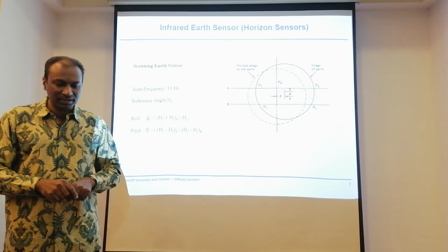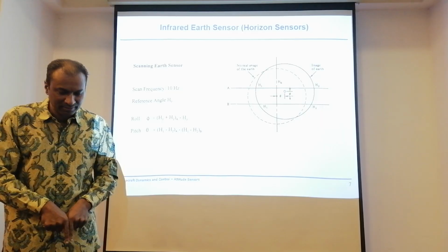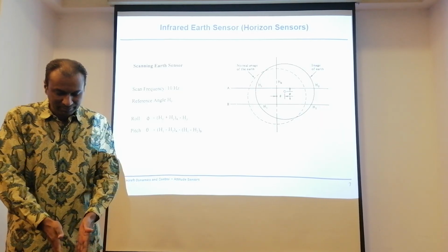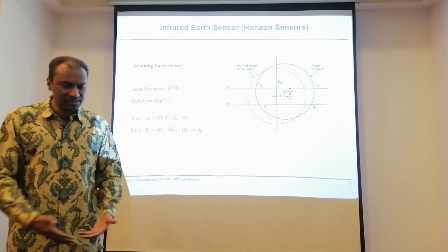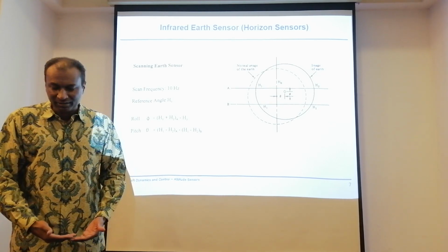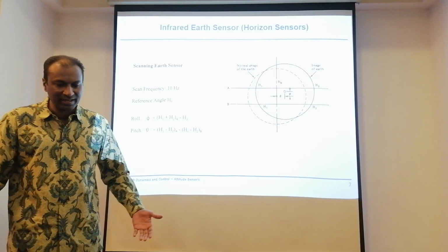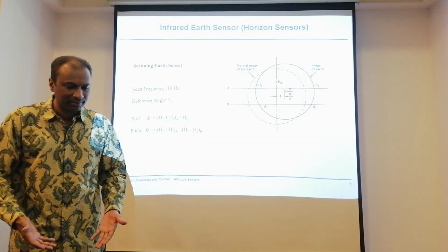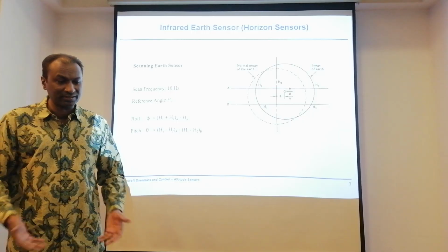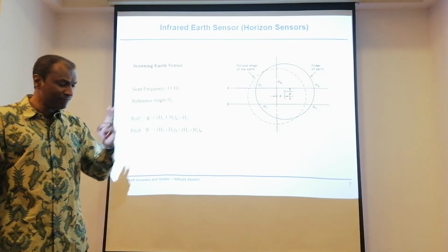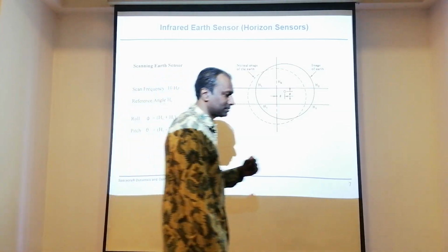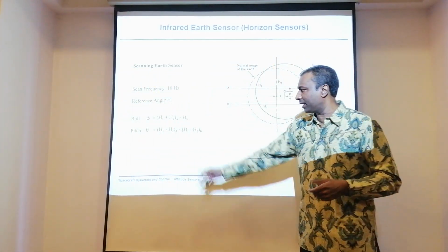But unfortunately, when you look down towards Z, that is exactly on the planet Earth. That means it's all basically the terrain. You can see sea, etc., so that you can't detect. You can't actually have a horizon. So you can only see the land. You can see it all, but you can't have the horizon. Which means that we can successfully have a detection of two major axes, roll and pitch.